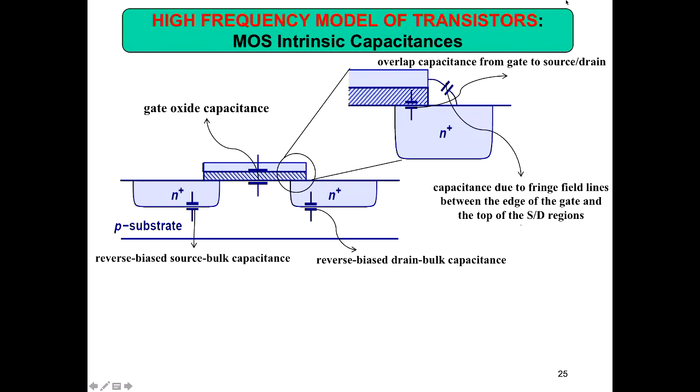That's a good question. For a person who worked in high frequency electronics in the beginning of my career, high frequency is above 1 gigahertz. Why I say 1 gigahertz is, you take a transistor, pump different frequencies, and plot the frequency response. All the major parasitic effects come into the picture around 1 gigahertz. You will be surprised to see how your signal is attenuated. Like you take a BJT and see the bandwidth, these days you can easily find around 500 megahertz bandwidth.